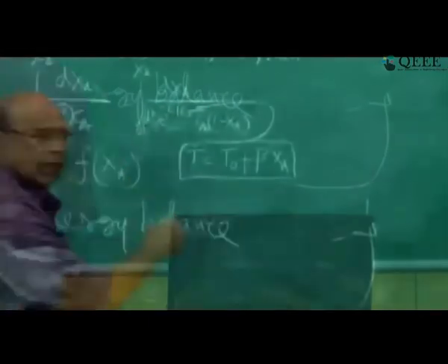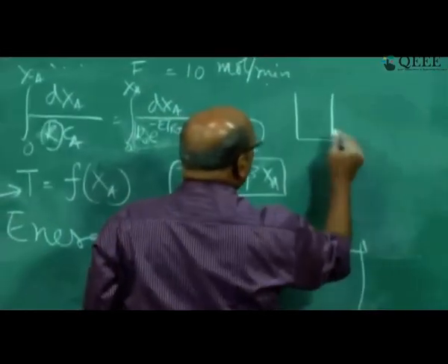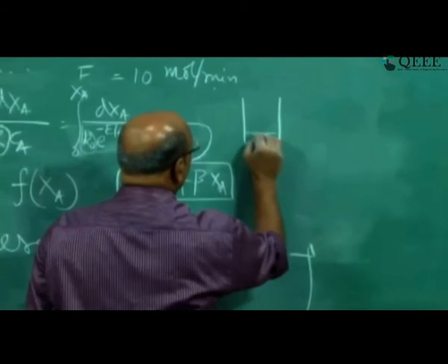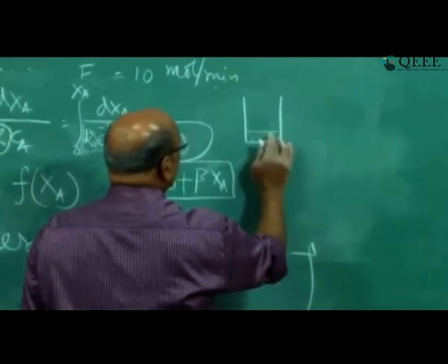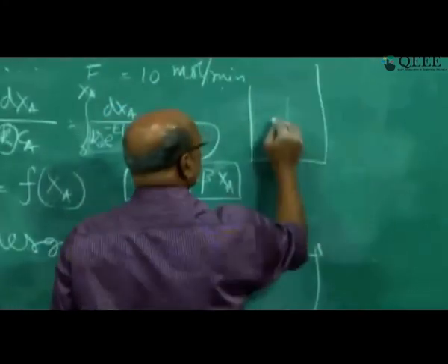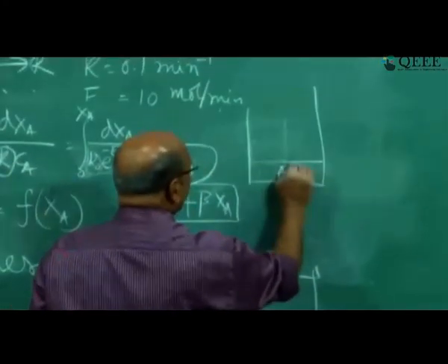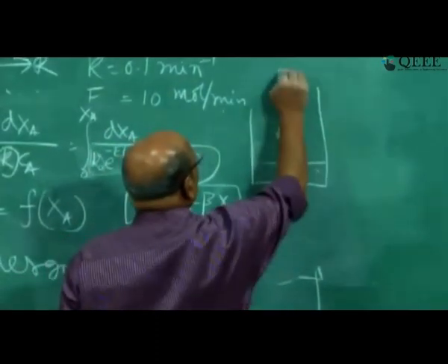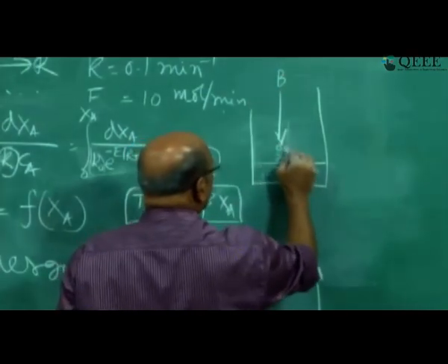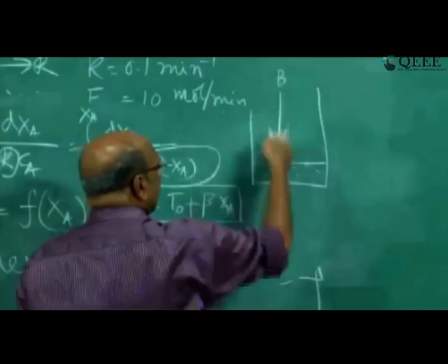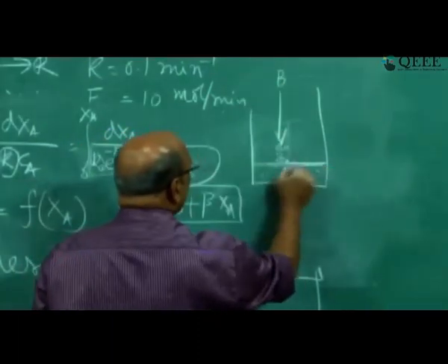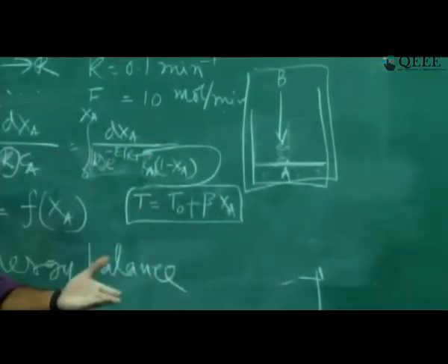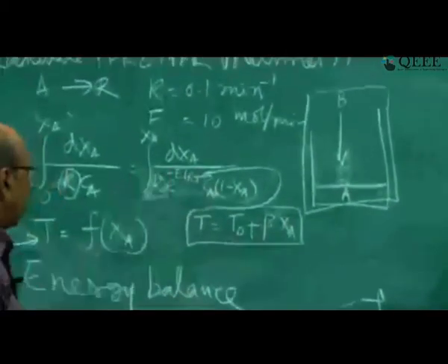Let me draw that. Okay. So now you take one reactor and I have two reactants to make it as fed batch. You take the reactant A here. This is A, already fed. And now slowly you add B, maybe drop by drop. Right? This is semi-continuous or fed batch. This is batch and now you are again feeding with some other thing. This analysis is totally different. So you cannot have mixed flow reactor as that of fed batch.